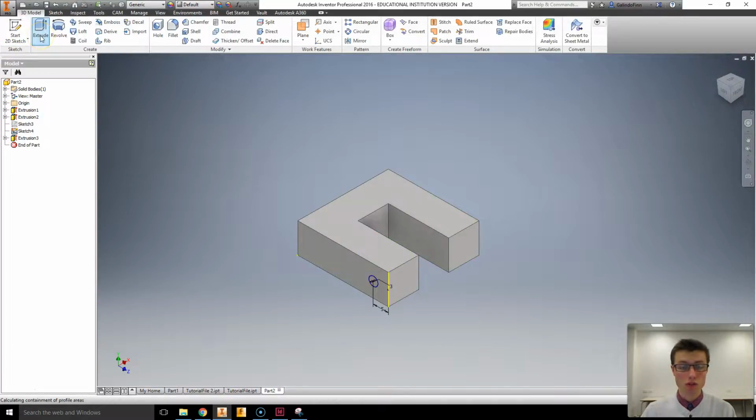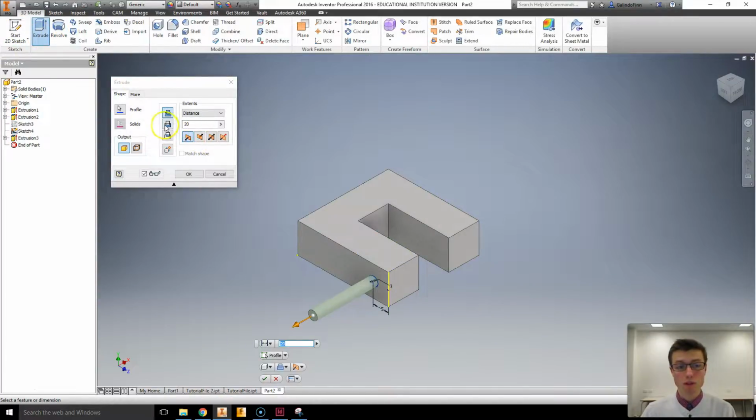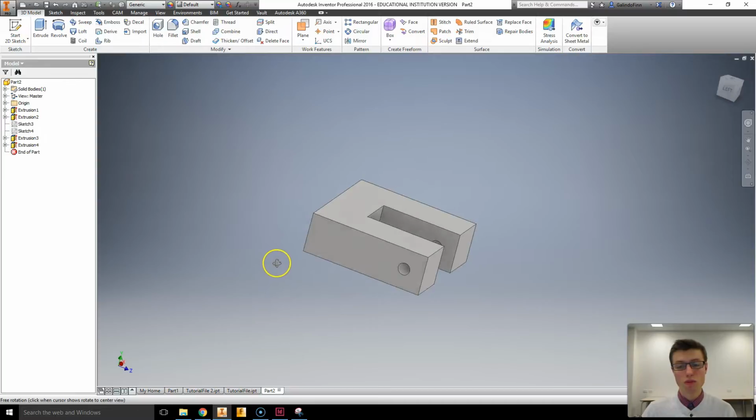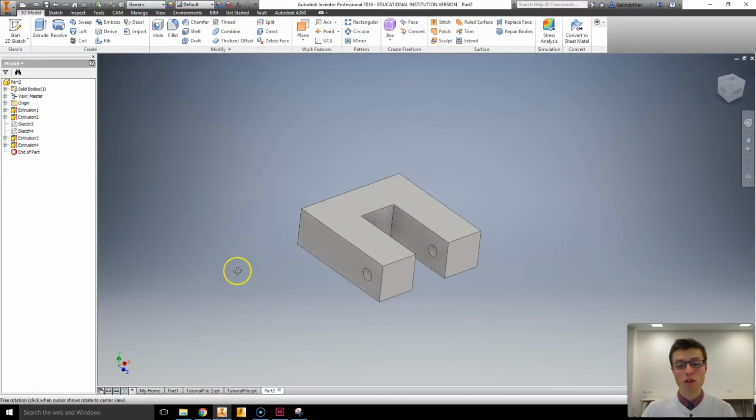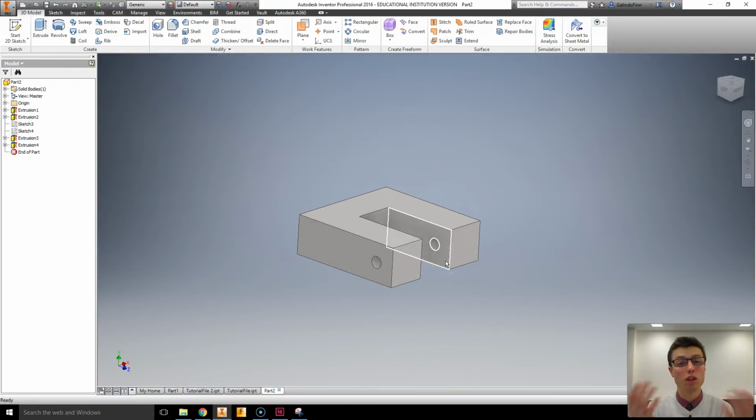You can also use extrusions to remove material. For example, if I select these options here, I could also have done it down here in the preview, in the smaller toolbox. I can then select either a distance or a different dimension style to next, as an example, or even through all, as an example. And you can see now how we can use the extrusion, revolution, and profiles to create features that then affect our part files, and thus enable us to design our 3D objects.